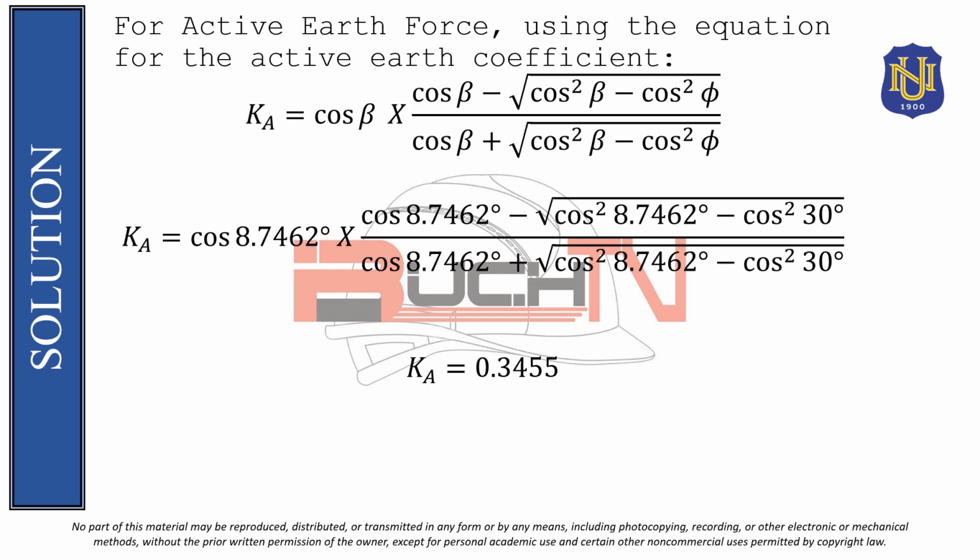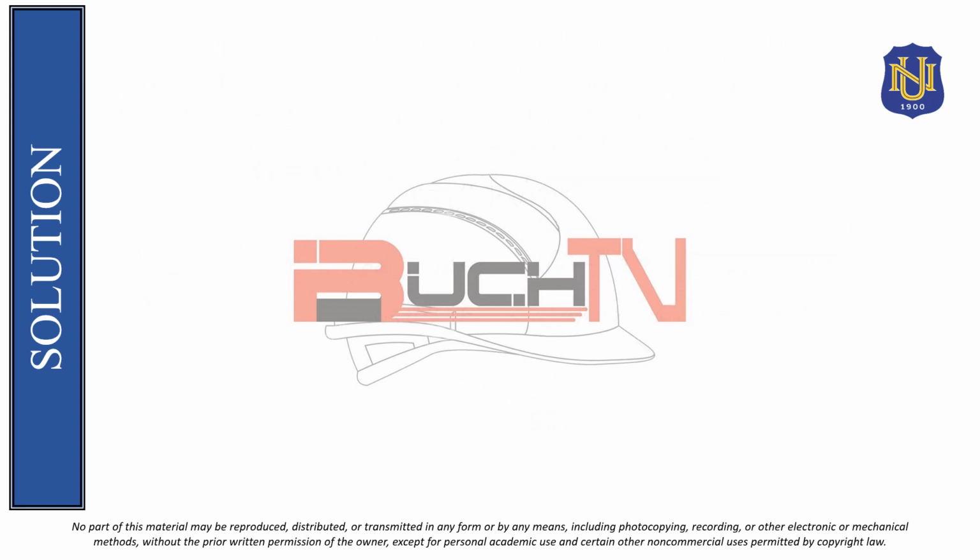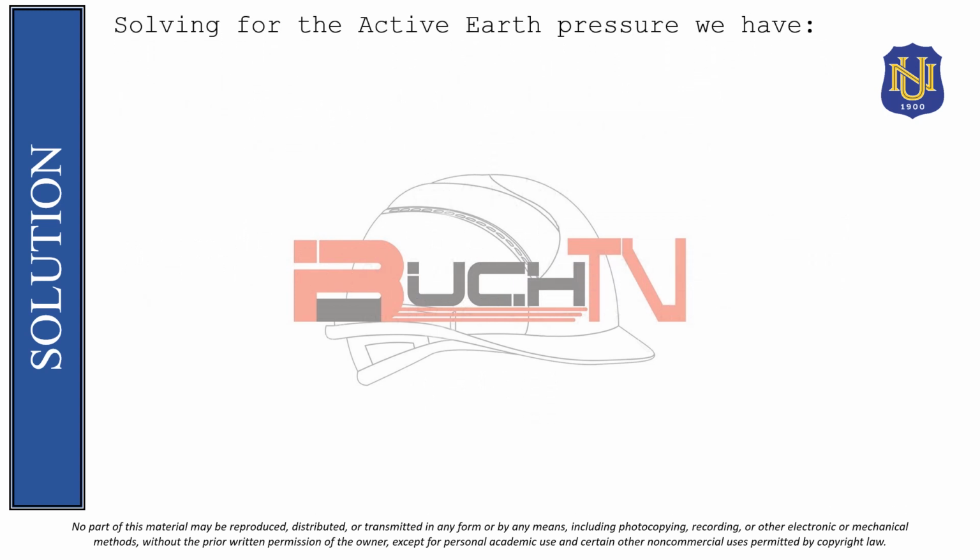After getting the active earth coefficient, we should now get the active earth force. So, solving for the active earth pressure, using the equation gamma H Ka, substituting gamma, which is 17.5, and the height of the retaining wall, which is 6.2 meters, we will have 17.5 kilonewton per cubic meter times 6.2 meters times 0.3455.